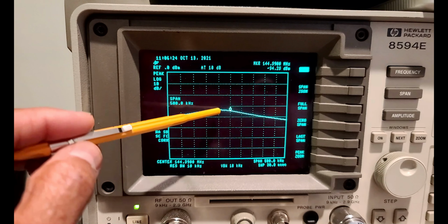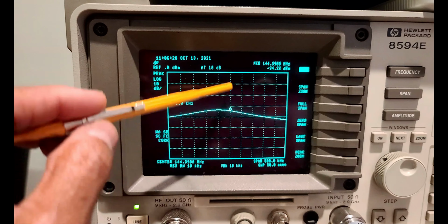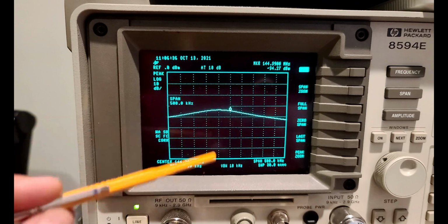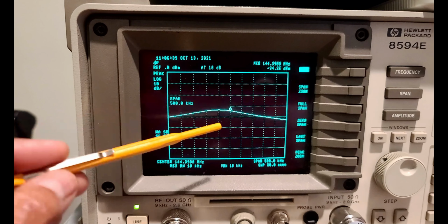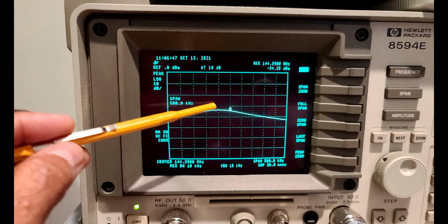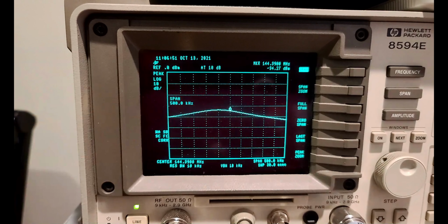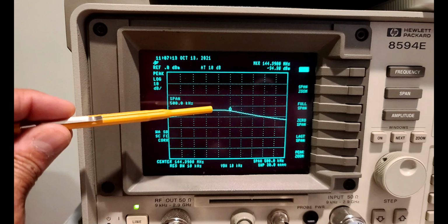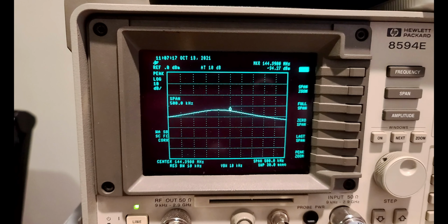It seems like there's a peak right at that point. However, we are tuned, the 144.39 is tuned at that location. So we need to be 100% precise with our 144.39 tuning. We need to move this peak to match with the marker. Right now it is maybe 5 kilohertz short of that precise tuning and resonance. So one way to do that is go back to our cavity filter and readjust the fine tune plunger and move this guy over toward the right and make sure we are tightly aligned.